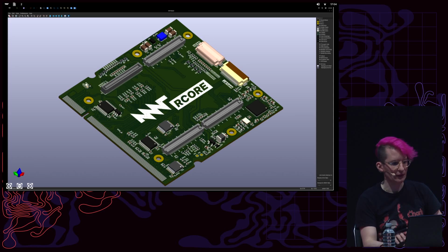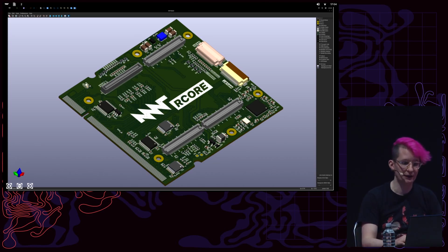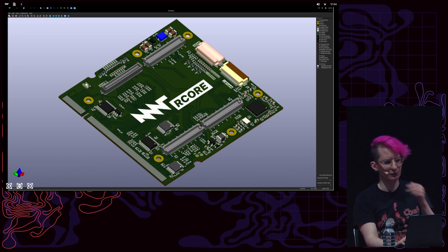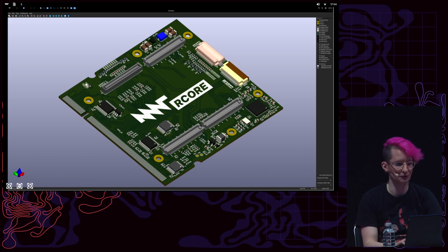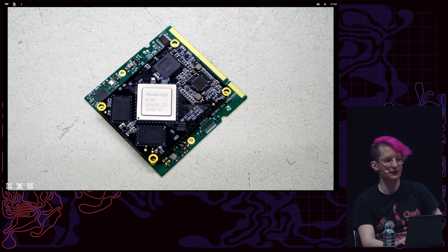In the meantime, Chinese chip company Rockchip had finally made a really decent ARM SoC that was surprisingly fast, including a good GPU, and the ability to address lots of RAM. It has 8 cores, 4 of them A76, and is made on an 8 nanometer process, so it doesn't use too much energy and can be passively cooled. I decided to start an adapter for the T-Firefly module with this processor once it became clear that a team around the open source company Collabora was heavily investing work in mainlining the drivers for this chip, and especially its GPU, which was the Panthor and now PanVK for Vulkan support project.